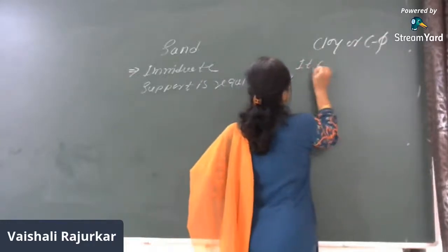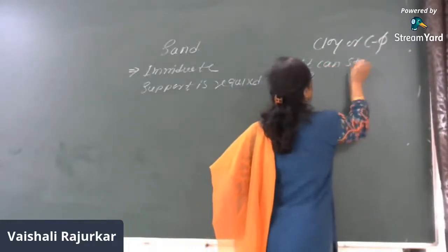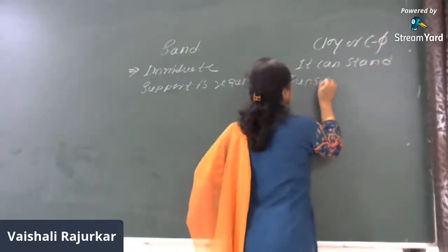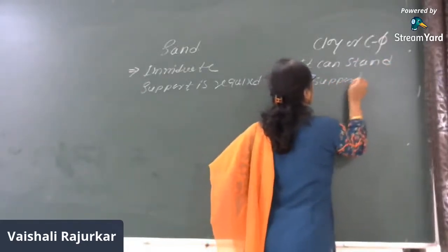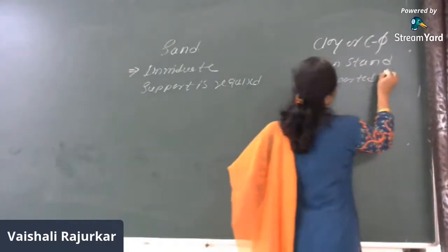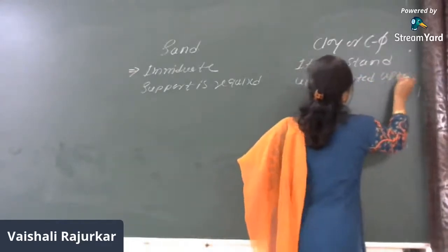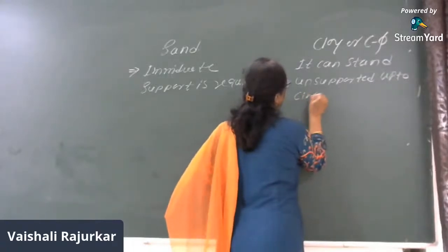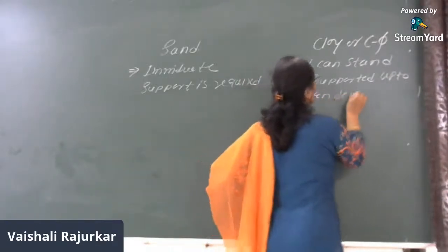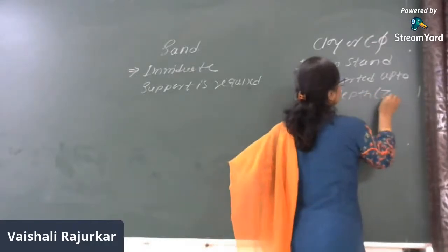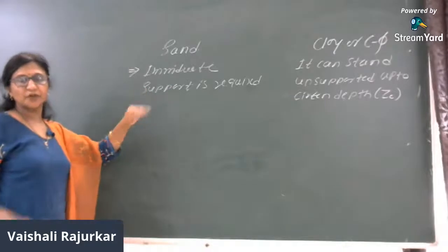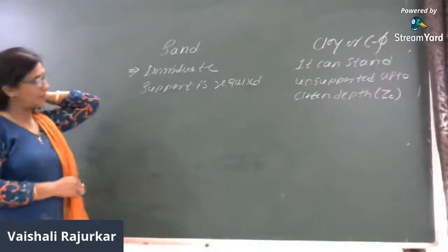It can stand unsupported up to a certain depth, and that depth is ZC. Means here we have to provide an immediate support when we make the excavation into such soils.